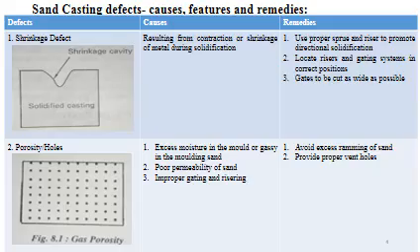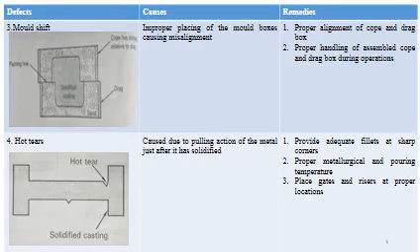Shrinkage defect, and porosity or holes or cavity provided in the component. The third defect is mold shift. The cope and drag boxes are not in a straight line; they are shifted to the right or left side. You can see this figure for a clear understanding.